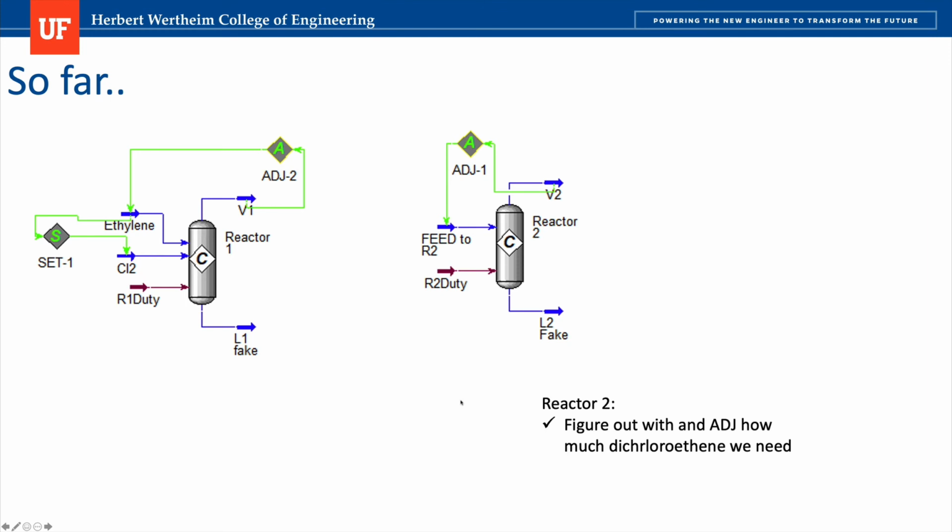So far, all of these heuristics help us to build the reactors. You may have one or two reactors, like here in the vinyl chloride example, where I have two reactors. You can use Adjust to calculate the feed composition based on the specifications on the product. You can also use Set, which allows you to calculate the amount of reactant compared to the limiting reactant, and this allows us to specify if the stoichiometry is 1:1, or if you have something in excess.